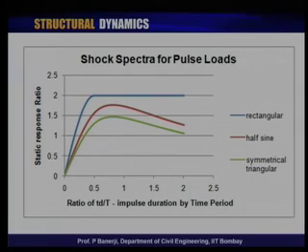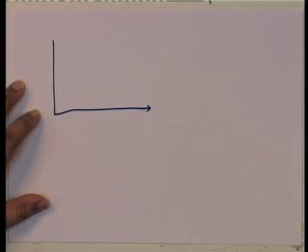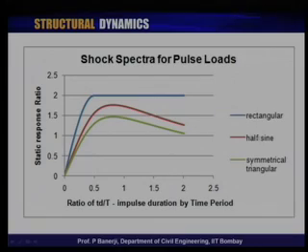So, shock spectrum actually gives you a full idea about how to go about it. Now I will do another specific short duration load before I move on to some other interesting kind of loading that you can do. Let us look at the short duration load. Another kind of short duration load is the one that I have drawn here, which is known as the half sine curve. Let us try to get this shock spectrum from our mathematics.